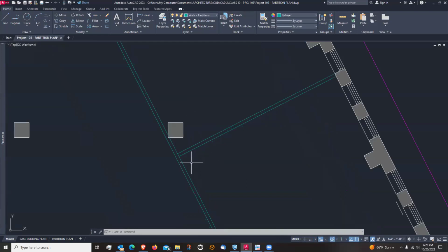And the first one is 3'4" from this corner here. So if I were to use the line tool and O track up on this angle, O tracking has problems with those angles, so I'm not going to do that. What I'm going to do is offset, which is perfectly fine. Another way to do it. So I'll just type O for offset, and I'm going to offset 3'4".